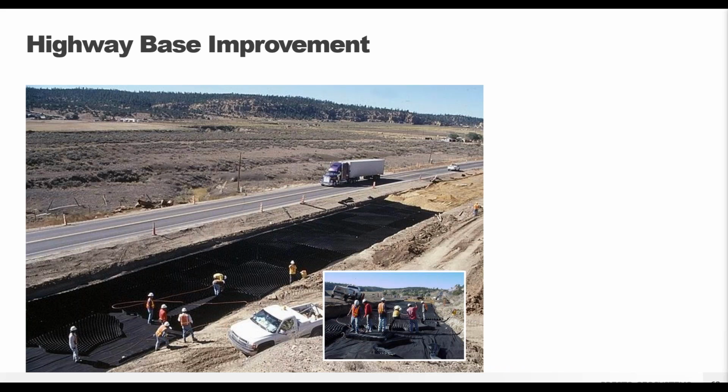So the GeoWeb system can be used under all types of roadways, from private drives to full service highways, like this project for the New Mexico State Highway and Transportation Department. So they were unable to proceed on a timely basis with any sort of conventional alternative, such as deep excavation with really thick base layers. They even considered using chemical stabilizers on the extremely soft subgrade, but eventually the DOT turned to the Presto GeoWeb system. The local sand material was used as the infill with the 6-inch deep GeoWeb system underneath a standard asphalt pavement.